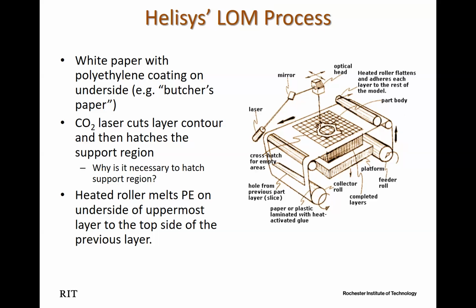But if they are hatched, you just tear them off from the printed part, right? And that's why you want to hatch the support regions in this process.